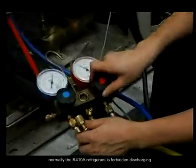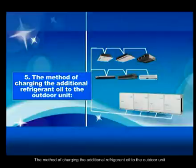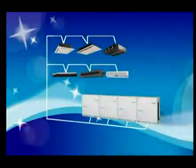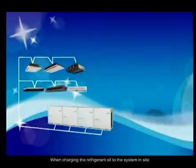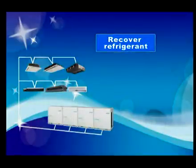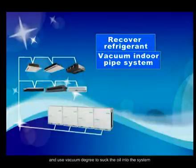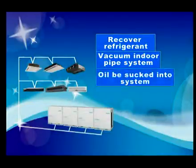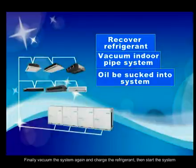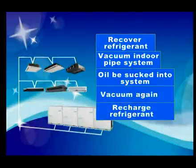Normally, discharging R410A refrigerant is forbidden. The method of charging additional refrigerant oil to the outdoor unit: when charging refrigerant oil to the system, the normal procedure is to first recycle the system refrigerant to the outdoor unit, then vacuum the indoor pipe system and use the vacuum to suck the oil into the system. Finally, vacuum the system again and charge the refrigerant, then start the system.